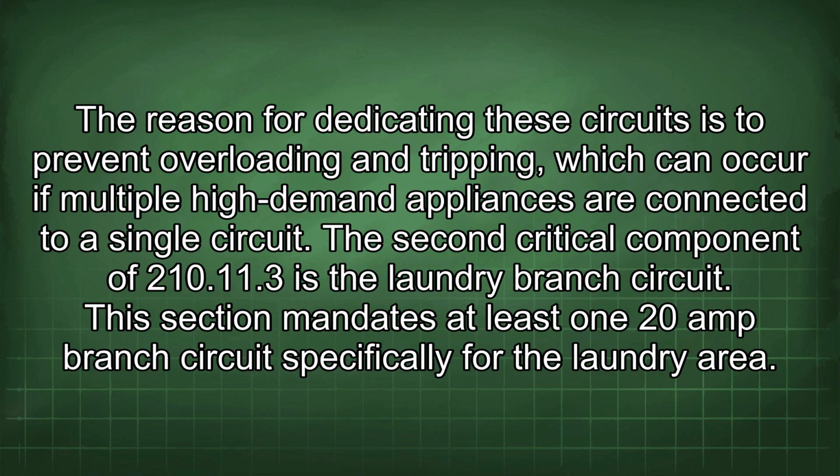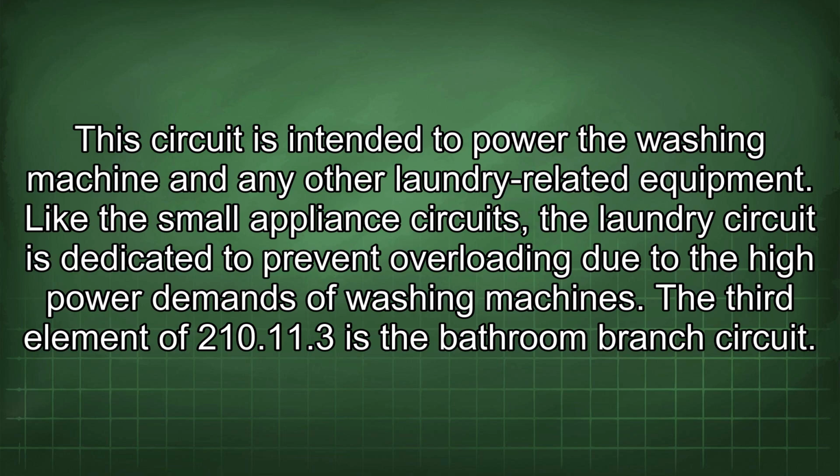The second critical component of 210.11.3 is the laundry branch circuit. This section mandates at least a 120 volt, 20 amp branch circuit specifically for the laundry area. This circuit is intended to power the washing machine and any other laundry-related equipment. Like the small appliance circuits, the laundry circuit is dedicated to prevent overloading due to the high power demands of